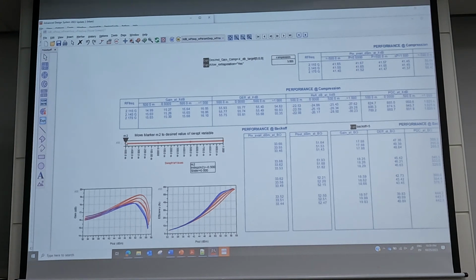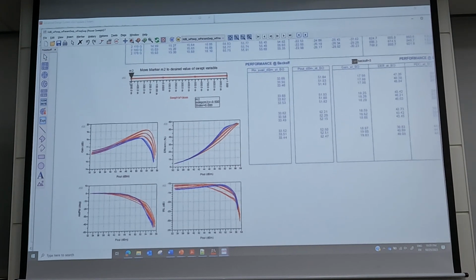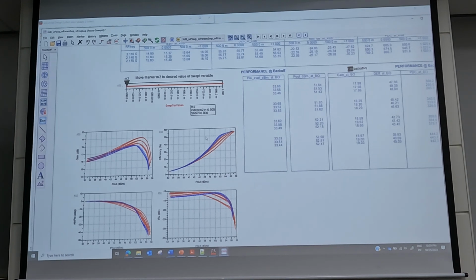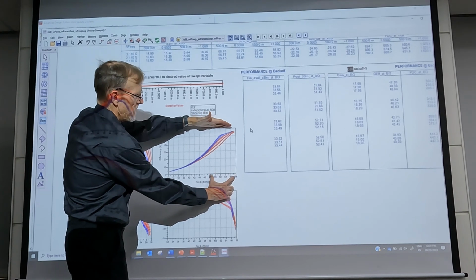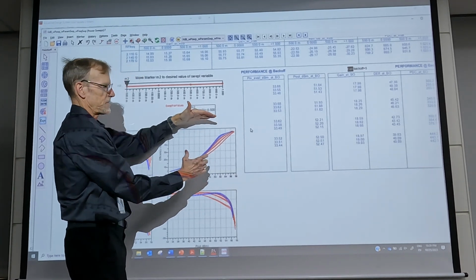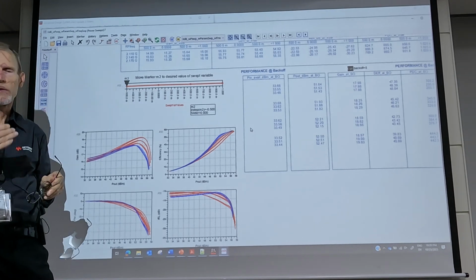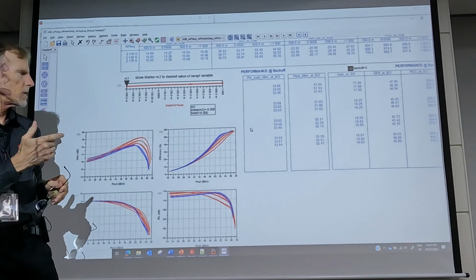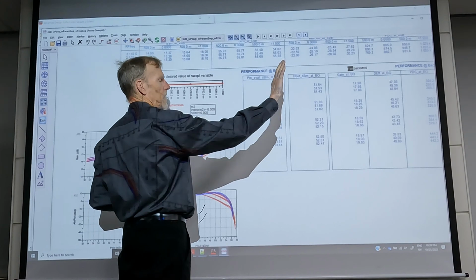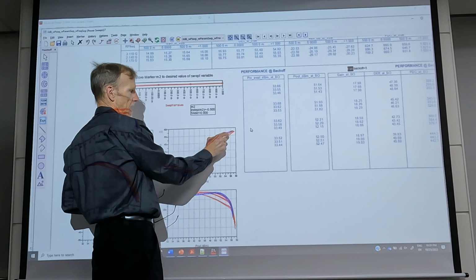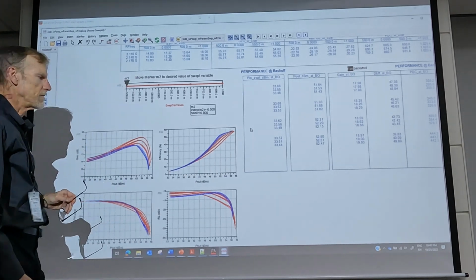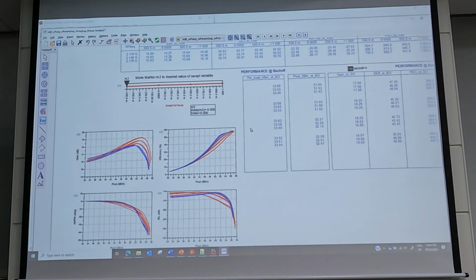These are the curves for gain and efficiency. This is close to what we want. We want to have a high efficiency over a range of output powers. That's the whole objective of the Doherty. You want to get high efficiency. You don't want high efficiency only at one output power. You want a range of output powers that still get high efficiency. So that looks pretty good.